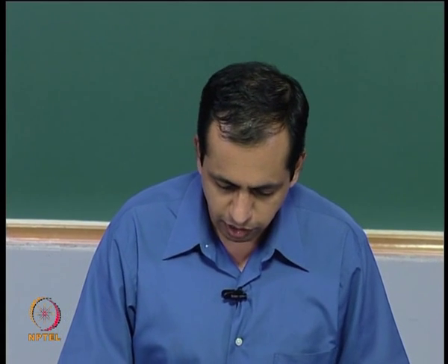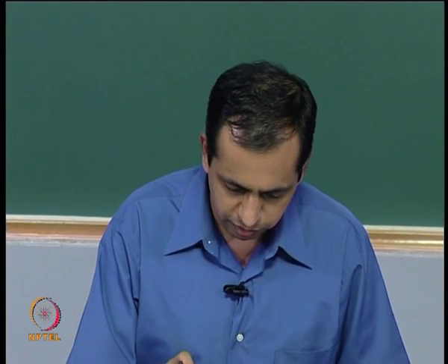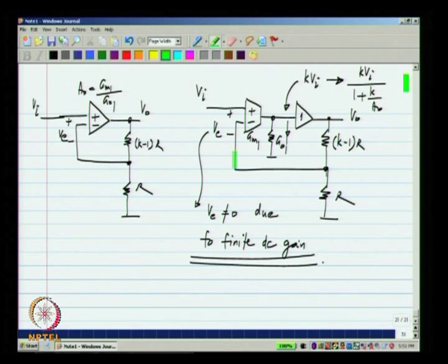Now, what is the desired outcome in a negative feedback system? The feedback quantity here must be exactly equal to that quantity there. In fact, with an ideal op amp that was happening, right. If you had an integrator without a finite DC gain, this is what was happening. Okay. There should be a capacitor here C1, that is what was going to happen. What we can do is, this is the actual value, we can compare it to the desired value and based on that control the current that is flowing there, okay, using an integrator.